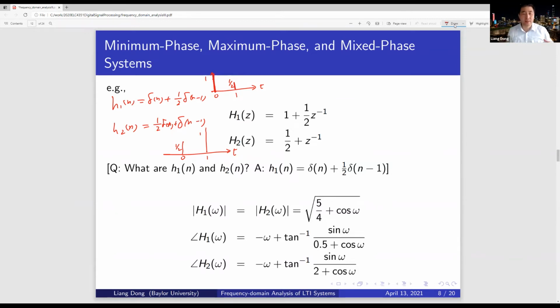So you have the input x[n], you get the y[n] output, and you don't have too much of a delay effect. Now compare with the second one. The incoming signal through this filter, x[n], becomes half of x[n], but you have a delayed term. This delayed term is relatively large. You have a large tail effect. If the energy of the system is dispersed over a large time delay, maybe it will give me a worse effect on my input signal x[n]. So we keep that in mind.